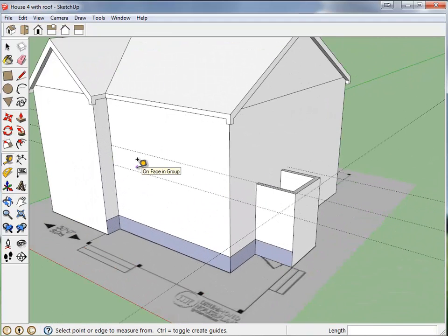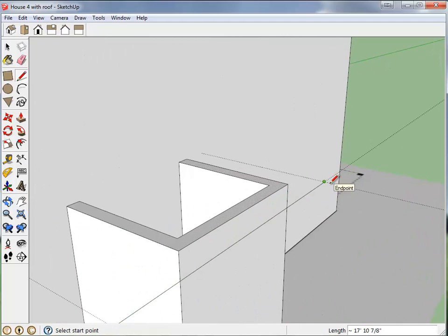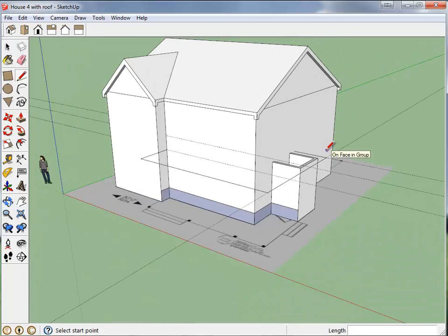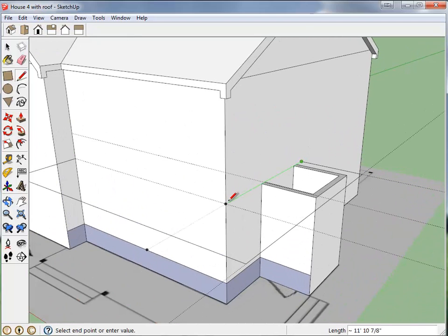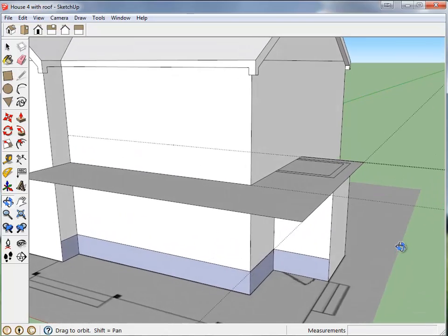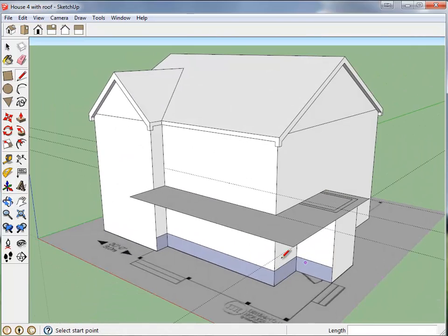Alright, now what we want to do is create the underside of the awning that will become the roof. Let's start by taking our straight line tool and pulling out 6 feet. You will then take a straight line down and connect to the guideline that we just drew. Then carefully trace around to the other guideline points up to the wall, making sure you're snapping your lines and creating perfectly straight lines. If done correctly, it will fill in as you see here.